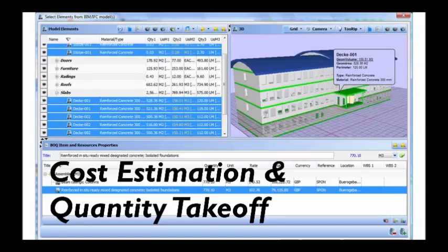But since you're introducing all these building systems, it becomes a lot more realistic and therefore a lot more specific in terms of cost. So it's a good idea to do another cost estimation during design development so you can see if the building is still on track budget-wise.